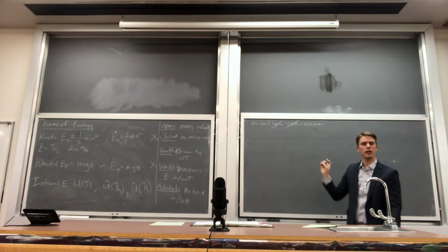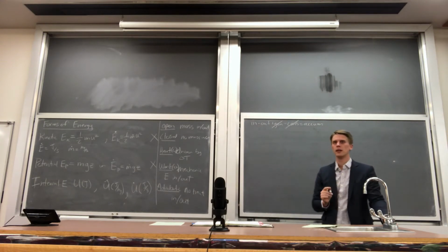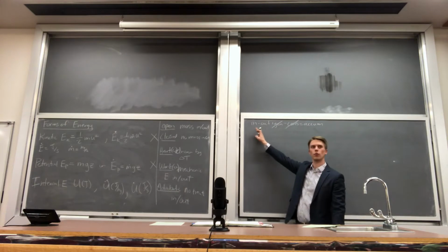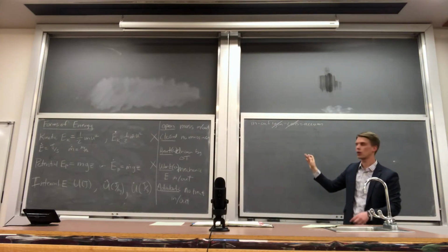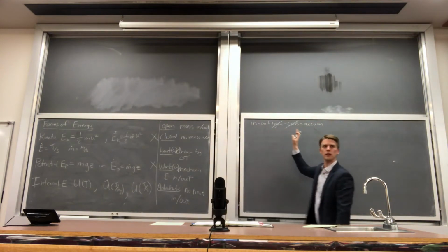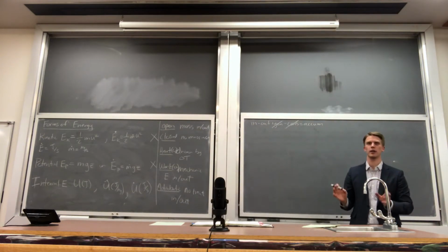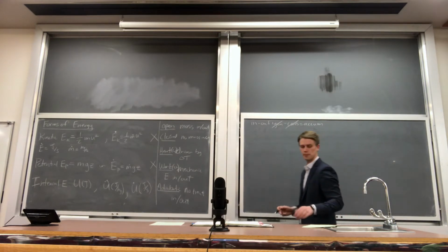Now that would be the difference form of the balance equation, right? We're looking at the rate of stuff in, the rate of stuff out, and the rate of accumulation. For a closed system where we're going to start off, this is driven by the initial, the final, and the accumulation. Like imagine it as a bucket, whatever you put in, whatever you take out, the rest is left there as an accumulation term.